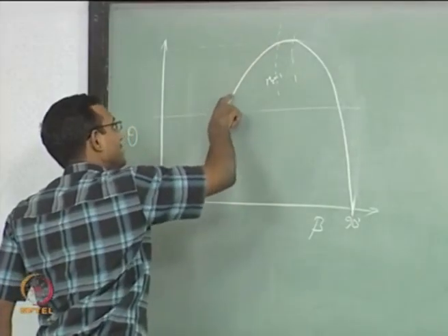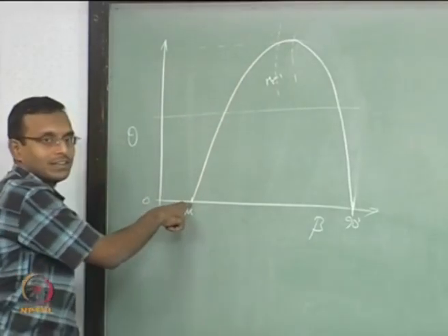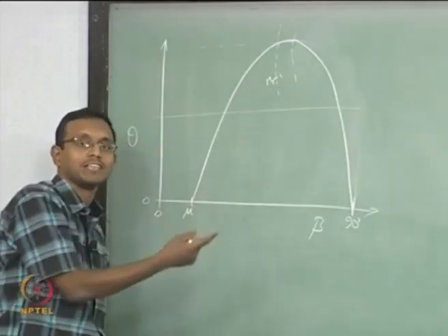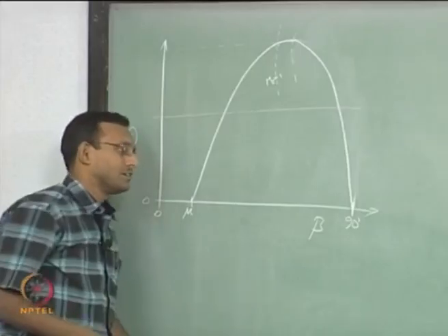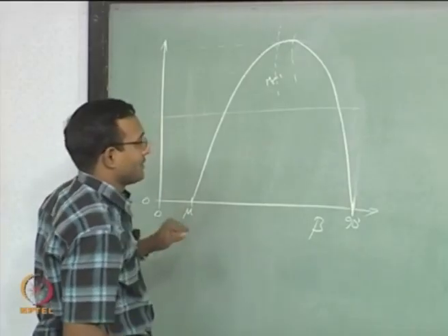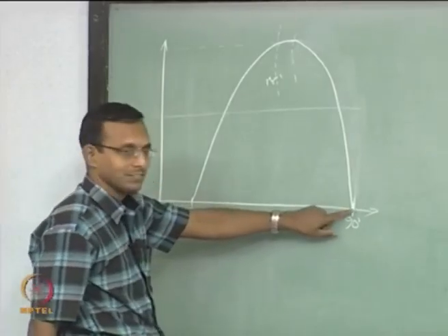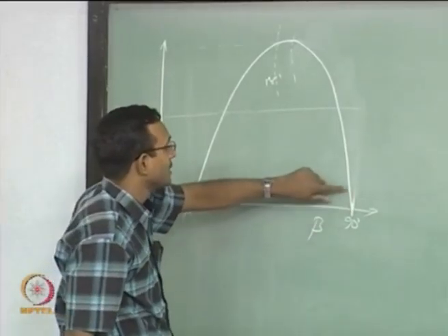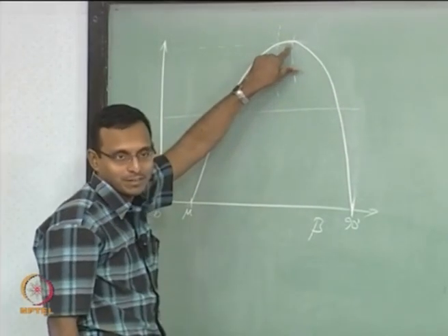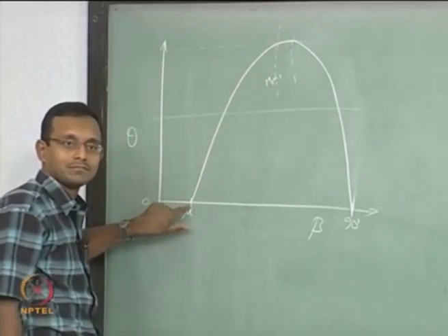After that it is further increasing to supersonic values up to a point where it becomes finally M2 equal to M1, goes all the way to there. Okay, that is, it is a Mach wave where there is no change, so M2 equal to M1 becomes that, it goes through the whole spectrum. Okay. The next thing I want to look at, theta value, this is more difficult. Theta value is 0 initially near the center, as it goes up it is increasing, goes up to the maximum value possible for that Mach number, theta max, and then it drops again and goes to 0 again.